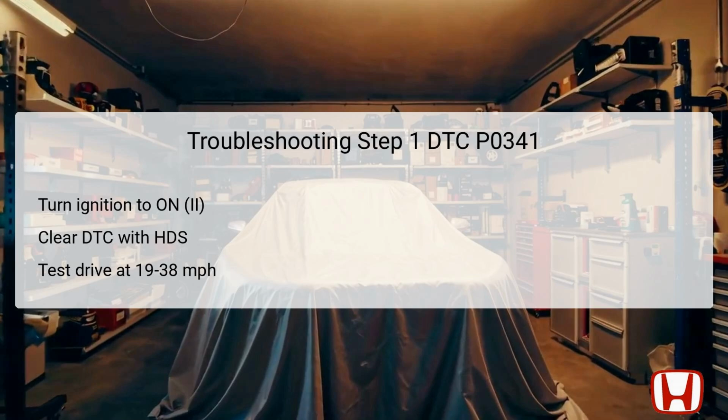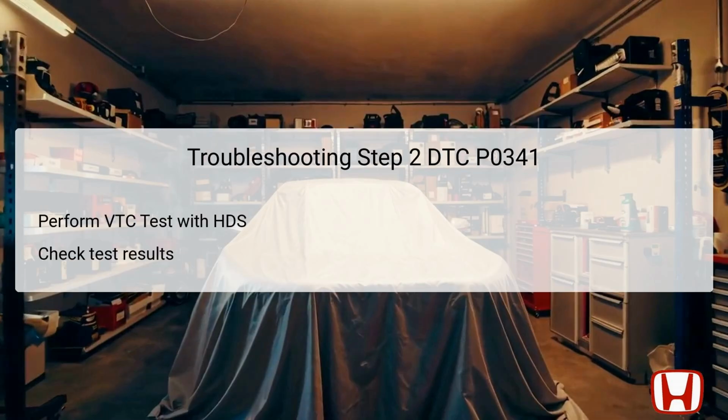If it does, proceed to the next step in troubleshooting. In Step 2, the focus shifts to evaluating the variable timing control (VTC) system. Utilizing the HDS, initiate the VTC test found in the inspection menu. This test is designed to analyze the performance of the VTC system, which is critical for the proper operation of both the CMP and CKP sensors.